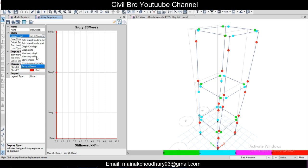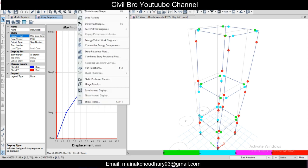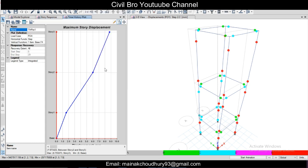Let's do this load combination PQX, and let's see the maximum story displacement here due to PQX. You can see this, it's around 9 mm. So this is the maximum story displacement here. So this you can do, and if you want, let's display the plot function.